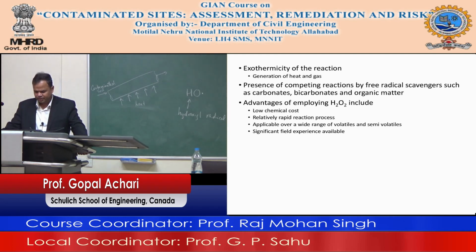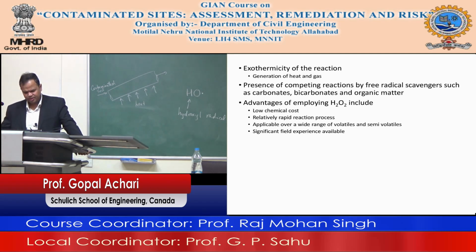So this is a system where you can see you apply chemicals. This one is an illustration. You apply the oxidant through those three pipes, as you see. It goes out through the holes on the side of the pipe and does its job, and pretty much that's what it is. So you don't have to actually take the soil out. You don't have to treat it anymore. You just inject it. Put your pipe in. Apply under pressure.